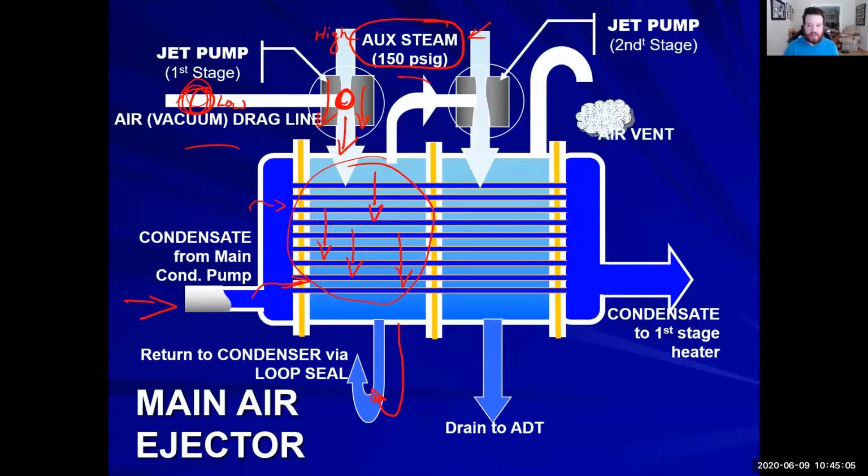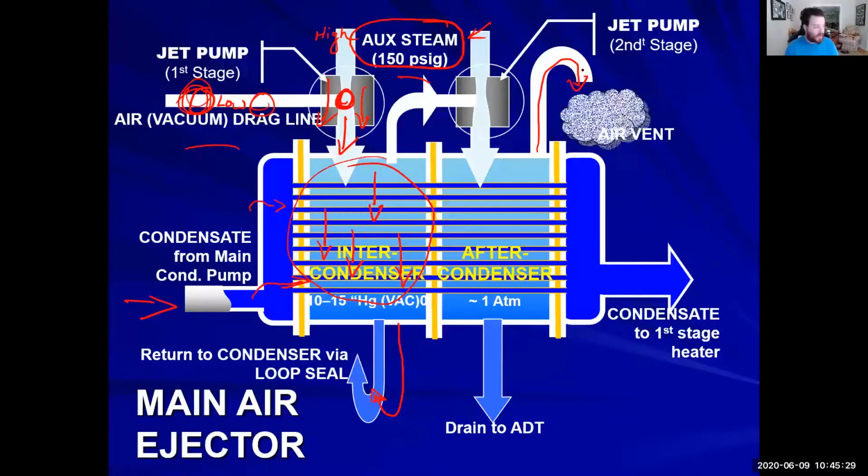Now we're going to talk about that second air ejector portion. It's a two-stage. All right. And its job is to pull out any of these non-condensable gases again. All right. And that whole effect is trying to just remove it. And that's what this gooseneck is. All right. You put your hand up underneath it during cruise, I encourage you. It's not going to hurt. It's not going to harm you in any way, but what you're going to be hit by is just little puffs. All right.